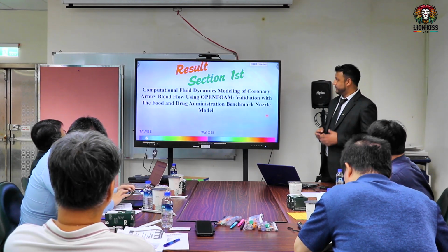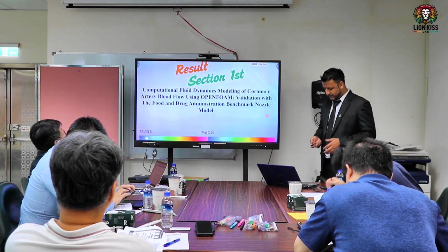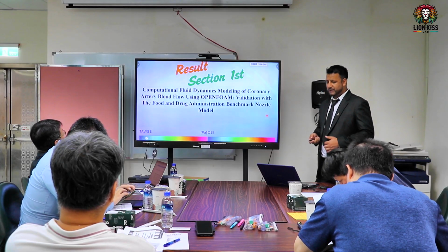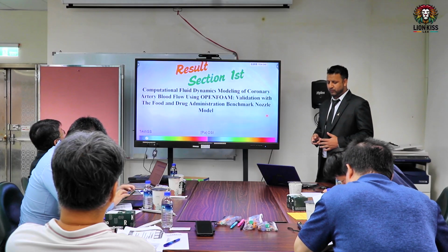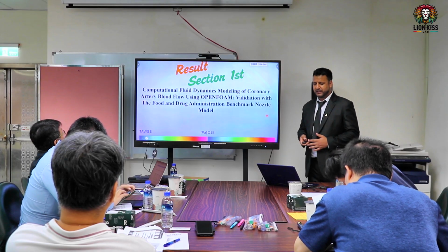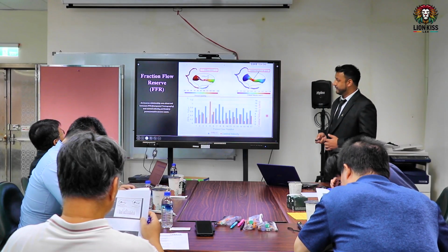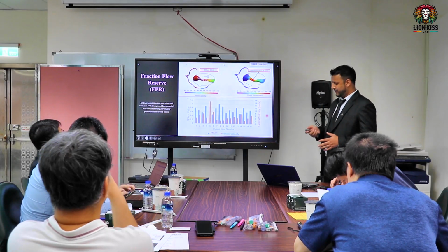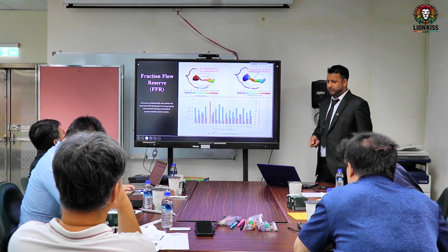So first we're going to discuss the first section, the paper we published. It's a computational fluid dynamics modeling of the coronary artery flow using OpenFOAM, validated with the Food and Drug Administration benchmark model. So first of all, we measured the fractional flow reserve, which is the division of pressure distal divided by pressure proximal.